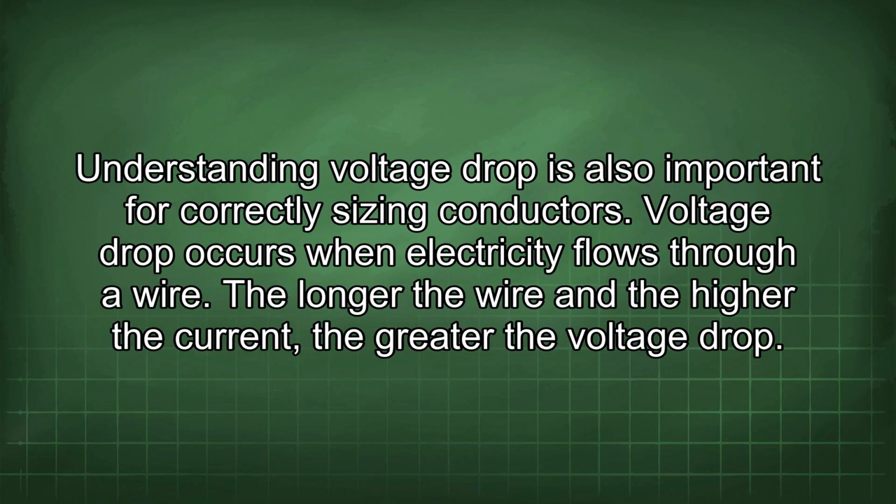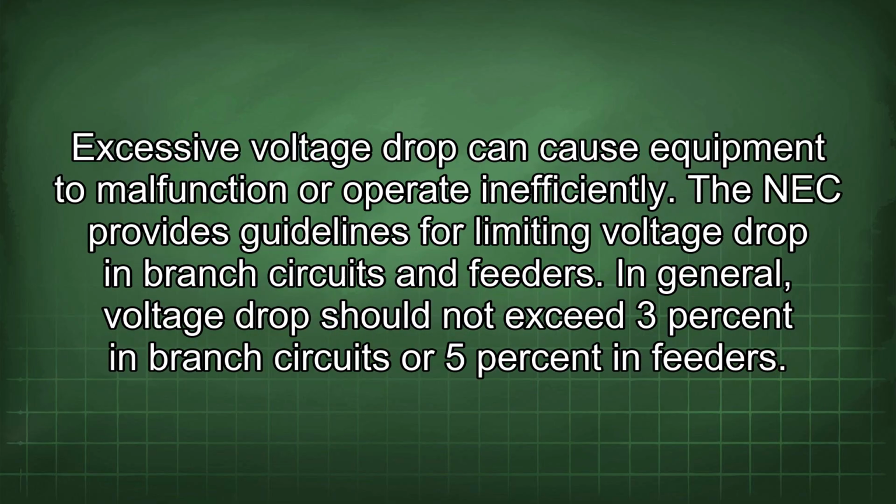Understanding voltage drop is also important for correctly sizing conductors. Voltage drop occurs when electricity flows through a wire. The longer the wire and the higher the current, the greater the voltage drop. Excessive voltage drop can cause equipment to malfunction or operate inefficiently.